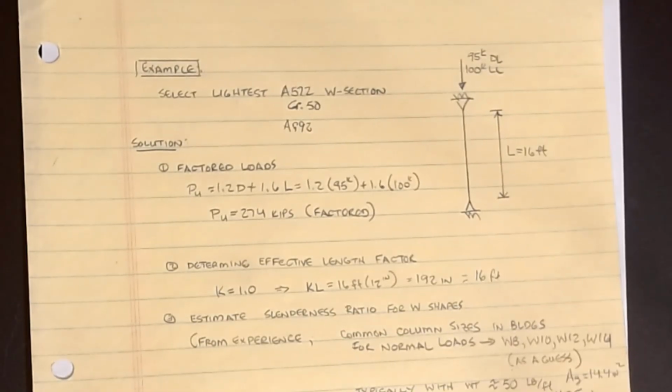Over the course of the last couple of videos, we've been talking about column strength and how we can use the AISC equations as well as the AISC tables to produce a result in a very quick manner. However, there are some exceptions to this methodology that we need to talk about today. In particular, what happens if a column is braced in one direction or another? How do we adjust those tables, since there was the requirement that it was only with respect to the y-axis that most of those tables were set up with? In this video, I'm going to explain what those differences are and show you how to handle them. So without further ado, let's get started.